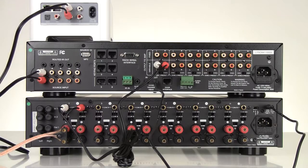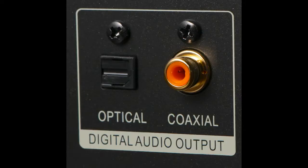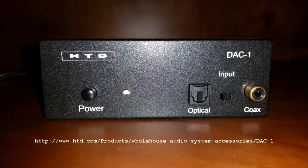Most audio sources will include an analog output that can be connected directly using a stereo RCA patch cable as we show here. If your source only includes a digital output, you will need to add a digital to analog converter before connecting to the Lync controller.